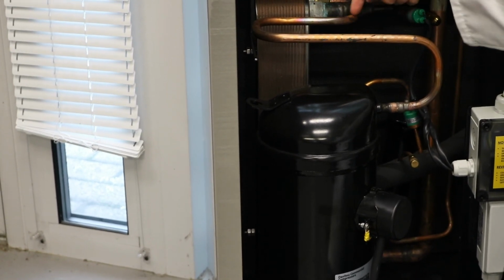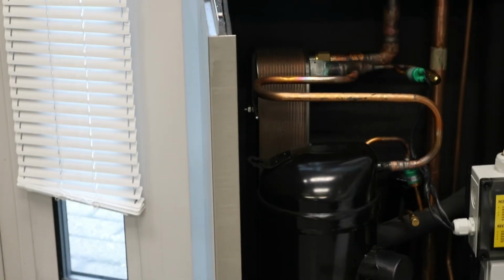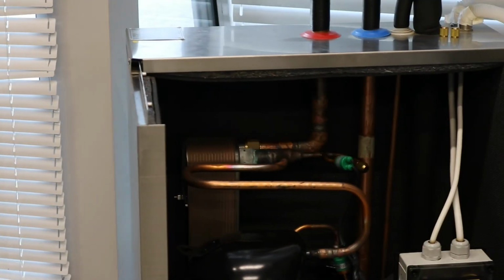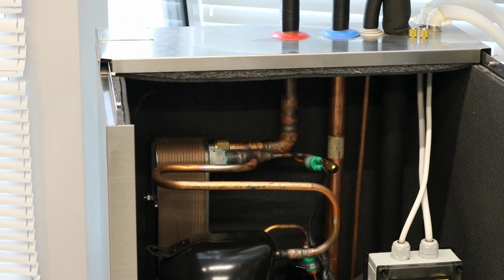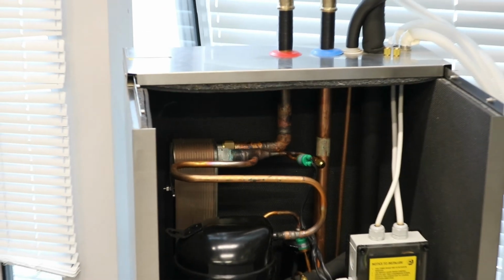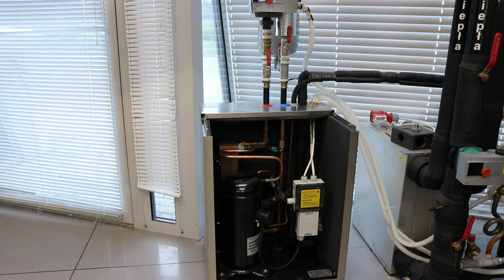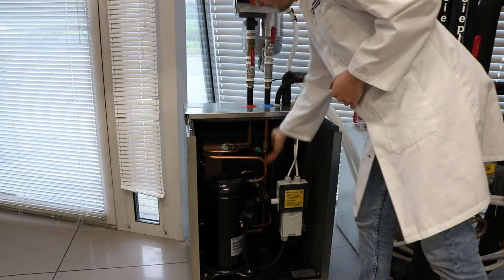We use the gases to transfer heat on one side and the heating system water on the other side. The temperature of the water rises and we can use this heat to heat our building. The temperature of the gas inside the heat pump falls down and it condenses to liquid. Such liquid is then transferred to the expansion valve right here.